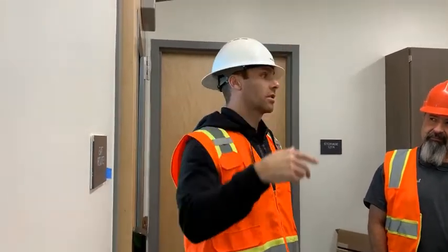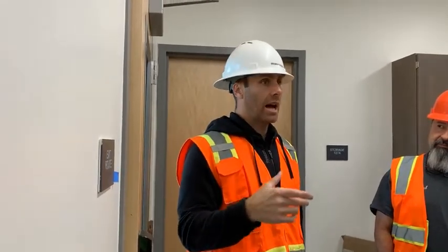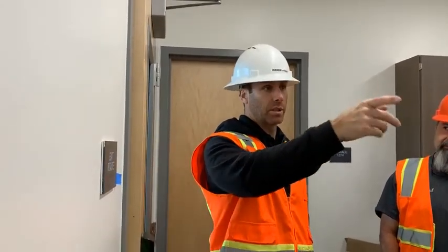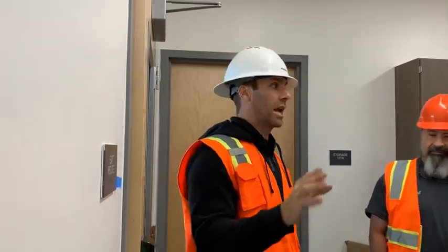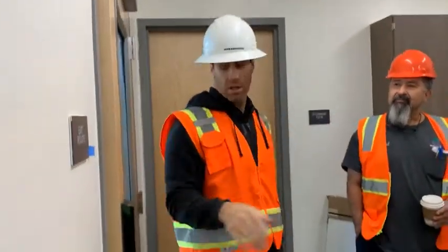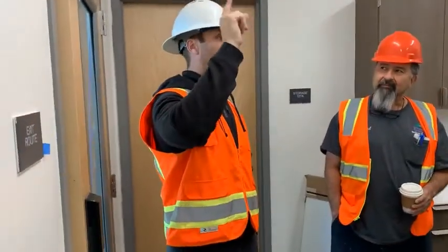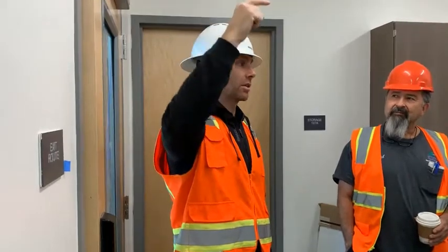Okay. When you have a room like this, it's pretty simple. Wall switch, fixtures. That's it. You guys did receptacle relays in the offices, right? Or no? I'm not sure. Okay. So realistically, all you would have, like in this room, are the fixtures. Coming out of here, you're going to have Cat 5 going from fixture to fixture, and you're just going to have power landed at each fixture. That's it.